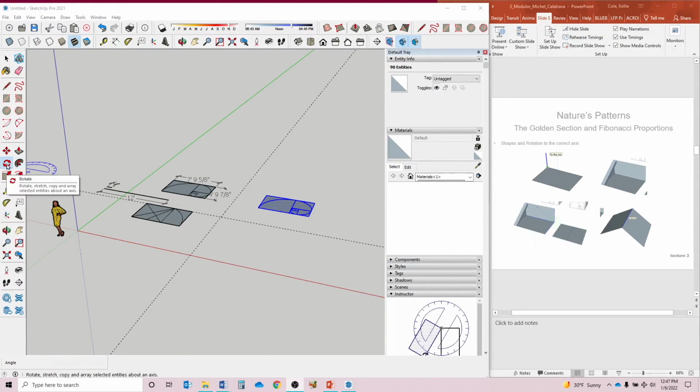This one has an odd keyboard shortcut command, as in that it's Q and not R. So we can hit Q or this rotation command. And notice how it's giving me a blue rotation, or blue protractor rather. I can use the directional arrows on my keyboard. So if I touch the up arrow, look at your arrows on your keyboard and push the right arrow. Push the left arrow. Notice how this changes the direction of rotation. So let's end on the right arrow.